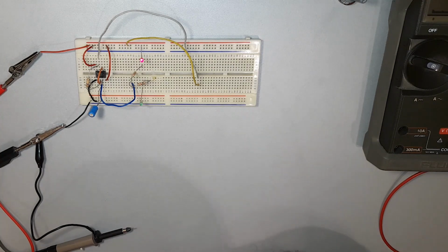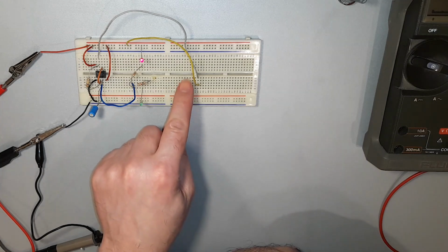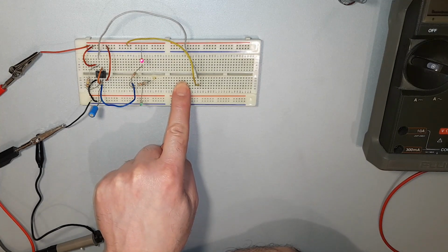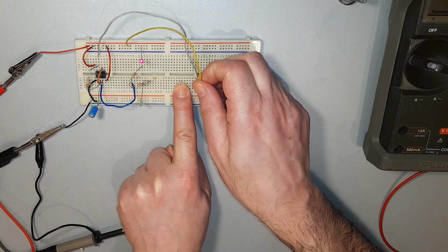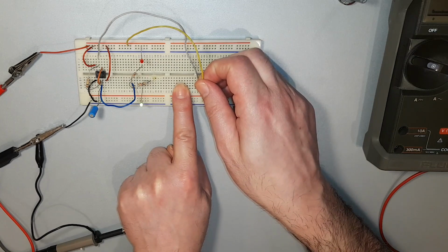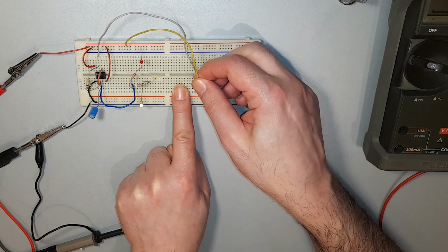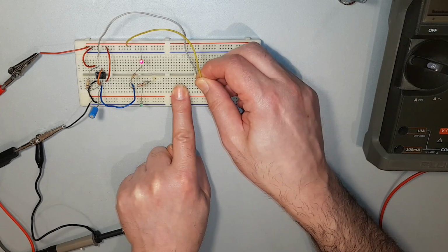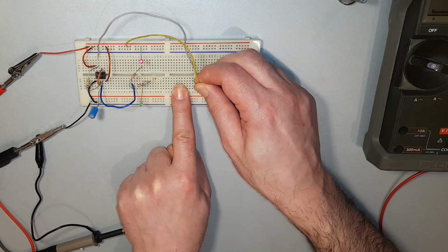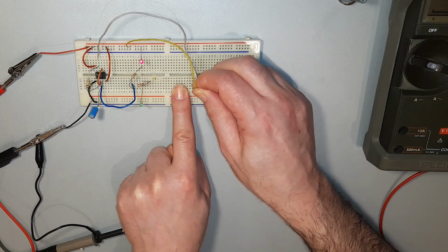I'm getting this reading from my power supply. So I've got a voltage of 9 volts and a short circuit current. That's this short circuit here from pin 8 to pin 7 has resulted in a 120 milliamp draw. When I take that out, it drops back down to 0. So that is a 120 milliamp short circuit current. Pin 8 to pin 7. Doesn't like that at all.